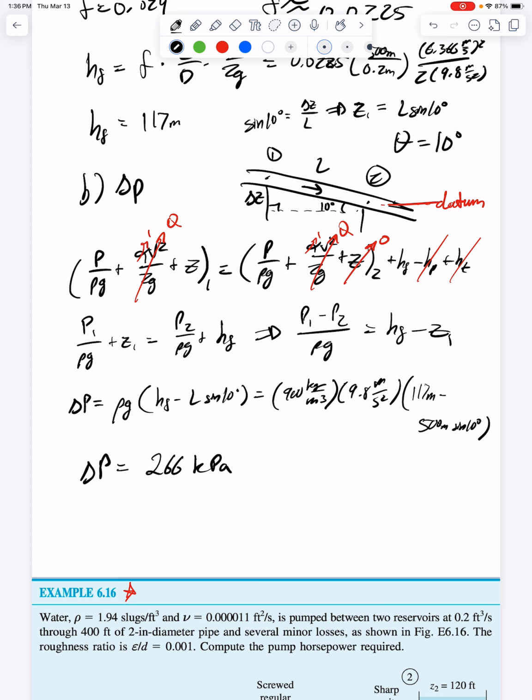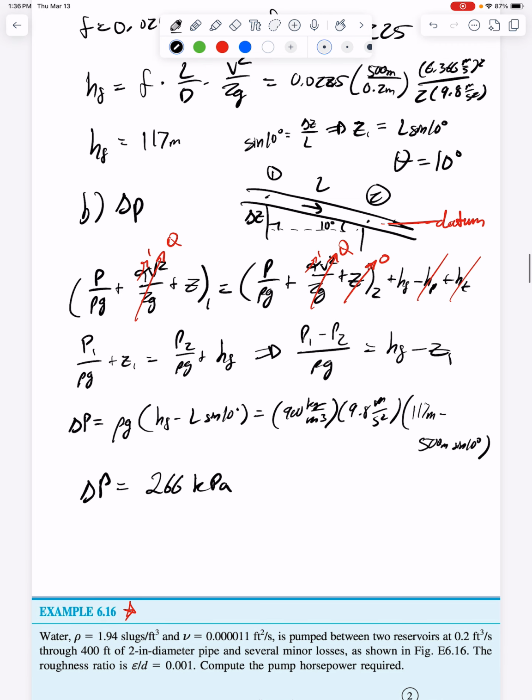Yes. Do we assume this is fully developed? Is that the reason why the velocity is present? Oh no, fully developed would mean alpha equals 2, by the way. Well, yes, the flow is fully developed, but the reason I crossed it out is that both locations have matching Q values, or volumetric flow rate. Even if it wasn't developed, Q should still be the same. But that's not the reason why I crossed it out.